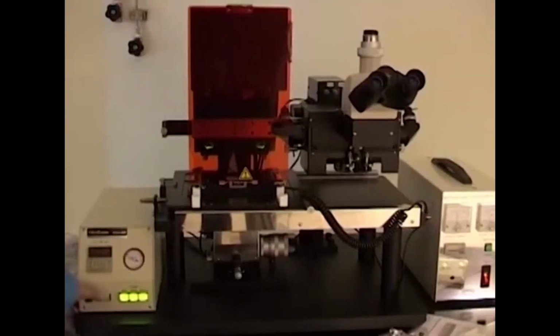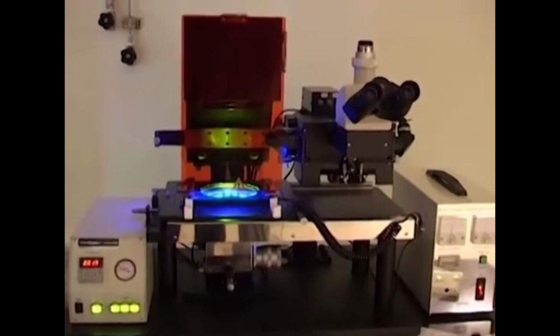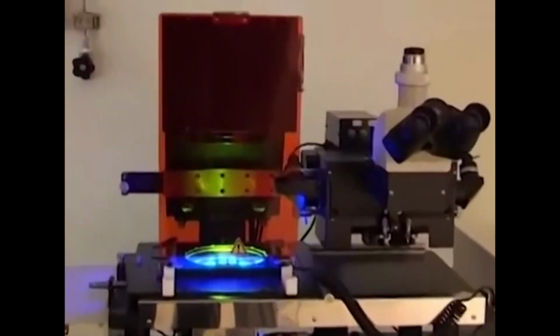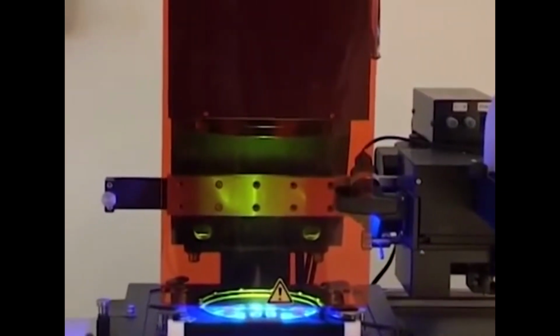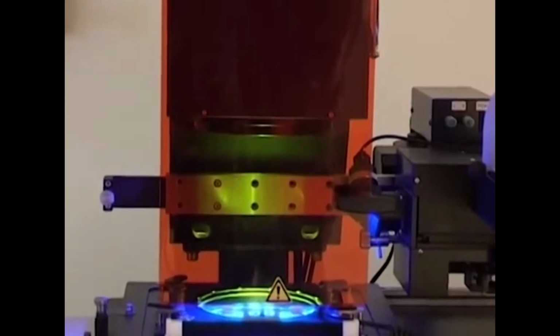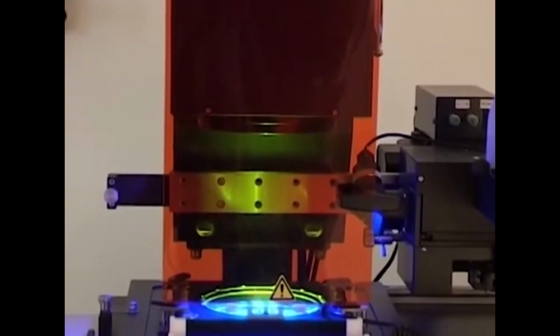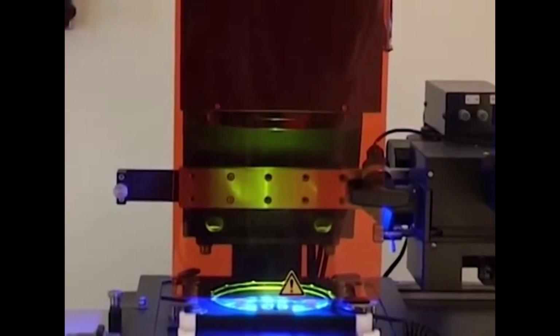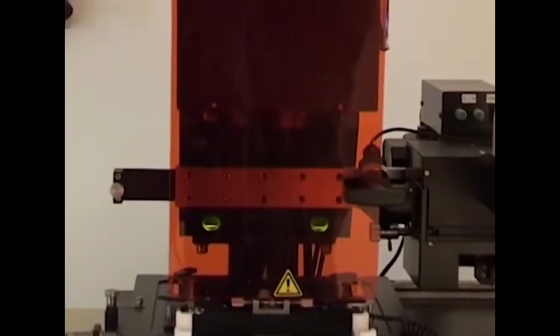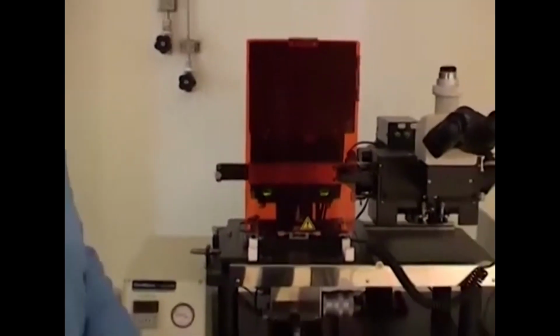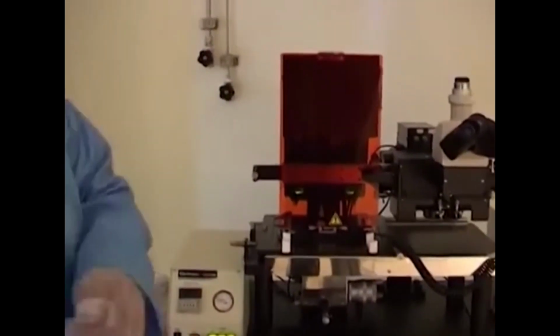I am now going to turn on the exposure light, and as you see here, the moment I turn it on, the timer clock has started, and the UV light is falling sharply onto the wafer. The time reading is rapidly reaching the 22-second mark that we had set before. The moment that is done, the exposure light will go off, and our exposure process of the photoresist is complete. As a matter of fact, it is just complete now. Now we have to unload the wafer and the mask, separate them, and then go for a post-exposure bake step that I will be explaining in the next step.